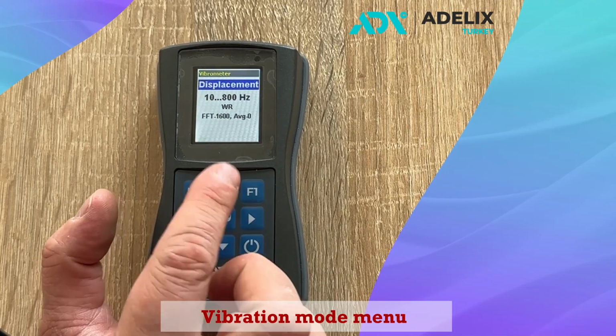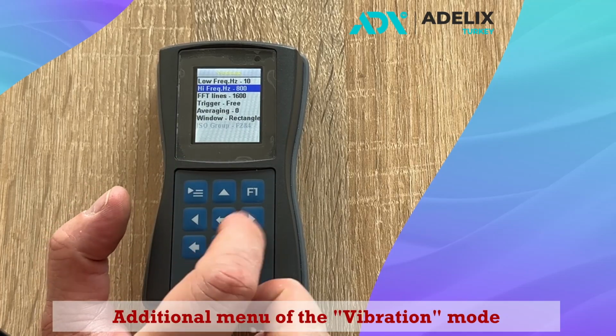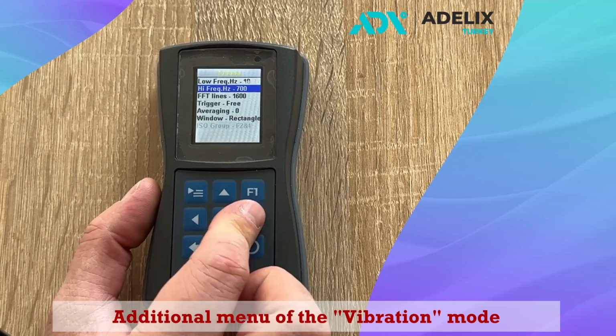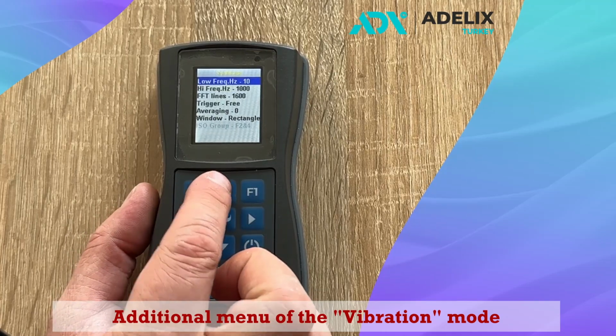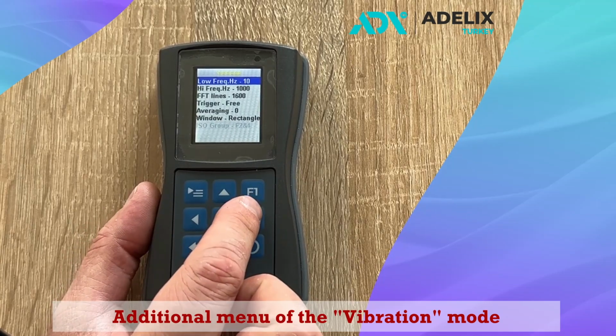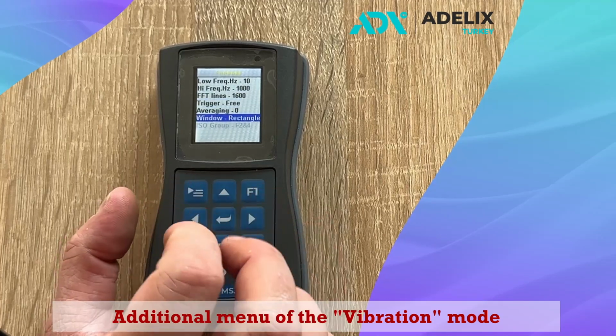By pressing the button on the device, we access the menu for configuring the vibration displacement mode. In the mode settings, we can adjust the frequency range, select the number of lines in the spectrum, choose between a free trigger or a carrier frequency trigger, set the number of averages, and also modify the display mode.